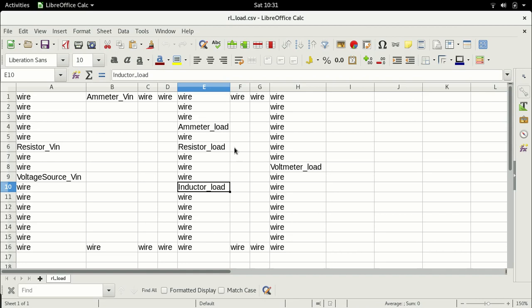First thing we need to understand is the purpose of how you model any particular machine or load. The very first step is you can just choose a resistor and inductor. That's it. The next step is to vary this resistor and inductor such that you can bring in some amount of variability into your load, rather than just have a fixed resistor and a fixed inductor.